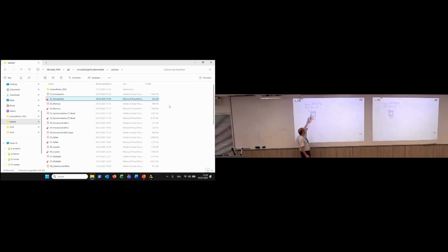And these are things that are placed by the designer because for the tool it would be very complex to do that. And you have an idea how your overall design should look. And then you place them more or less just so that you have a lot of area for the logic left, and for the routing.